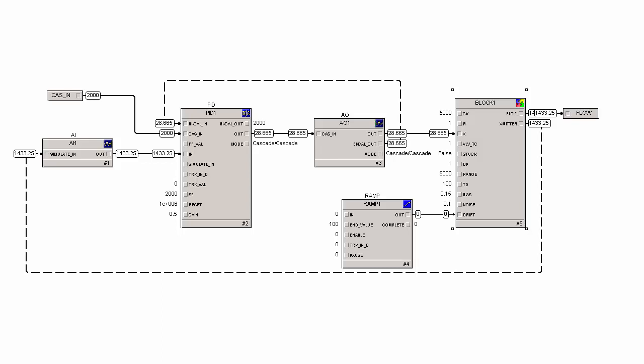So now I want to demonstrate what will happen if we had a valve that got stuck while we were doing set point changes. So once again, reset time is in essence a proportional only controller, and I've added this extra feature, drift, so I can drift the valve and I can stick it.